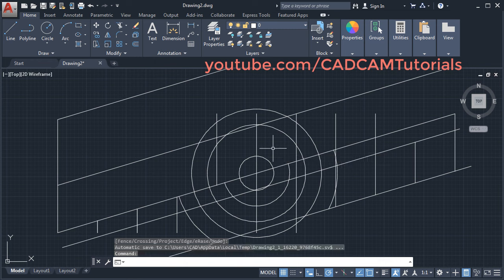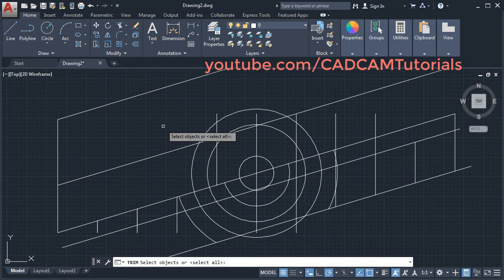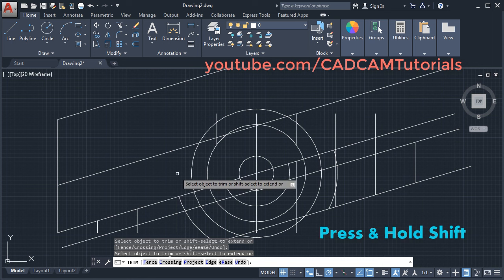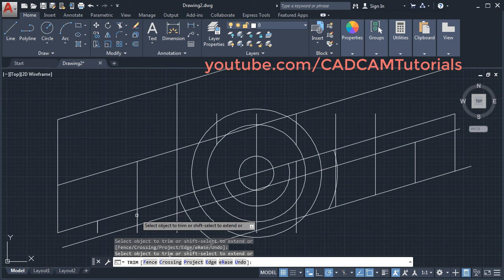Then you can also use trim as an extend command. Suppose I again click on trim, then I will press enter to define all objects as cutting edges. So now you can trim it. But suppose I want to extend some object, then here is the option shift select to extend. That means you will have to press the shift button and click on the object you want to extend. In this way you can use trim as an extend also.